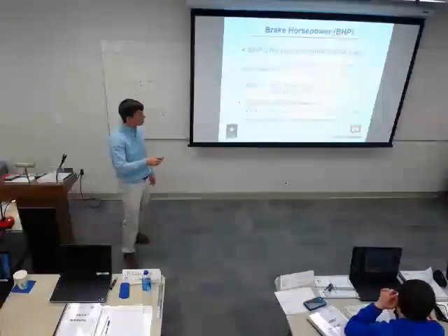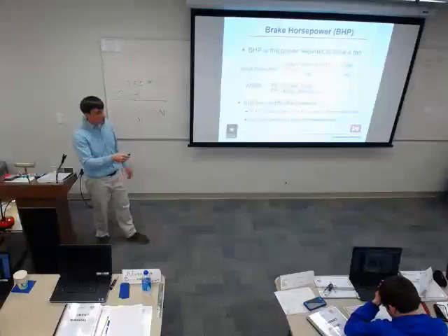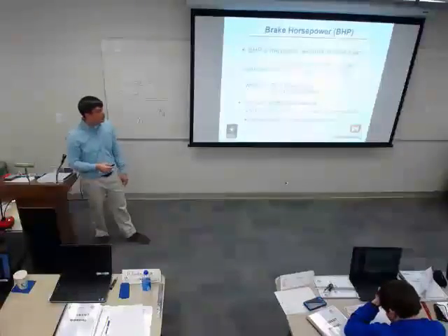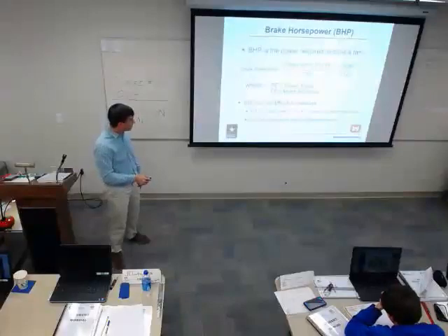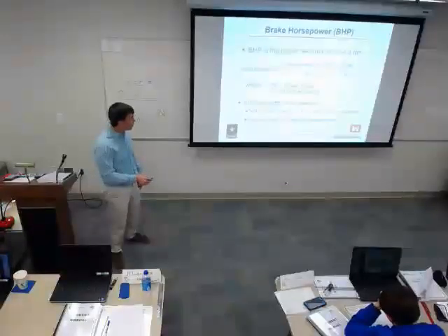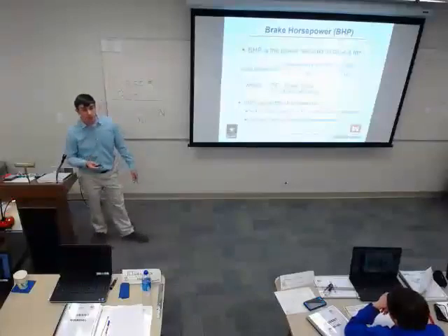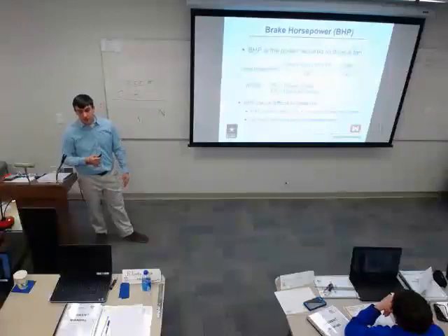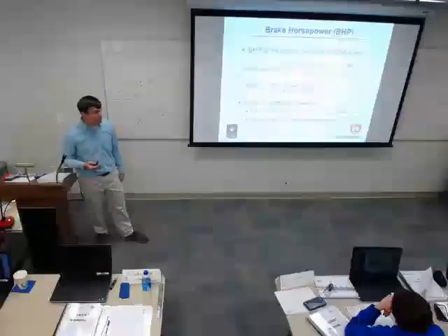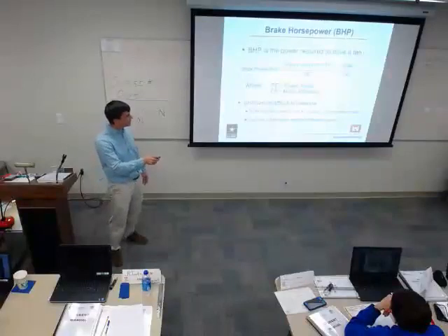And I need to know the efficiency of the motor, which is published on the motor. But the efficiency of the motor changes depending on what speed it's running at. So, point being, for a motor, it's not as simple as volts times amps, like it would be for a resistive load, a resistive load being a heating element. The motor adds an inductive element to it and brings in this power factor.